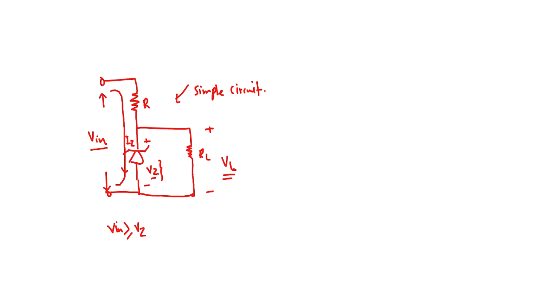So if there is a change in the load current, for example, an increment or decrement in the load current, the zener diode current IZ gets adjusted, and therefore the total current I, which is IZ plus IL. So if IL goes up or down, IZ goes down or up respectively to maintain the same current I. And accordingly, you see that the VZ is always constant across the load. And that's how you maintain the output voltage constant irrespective of the changes.